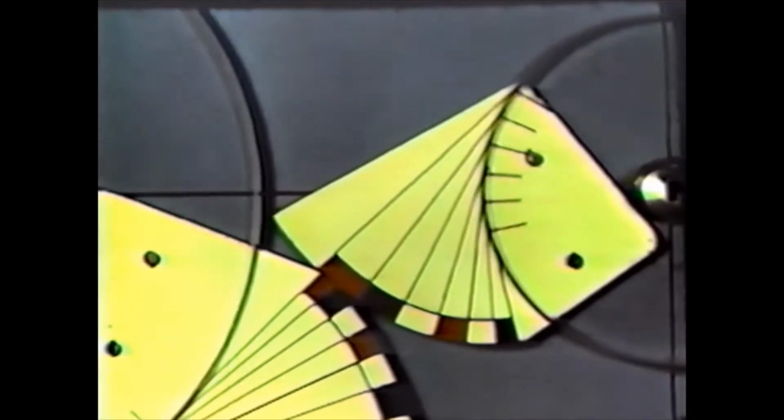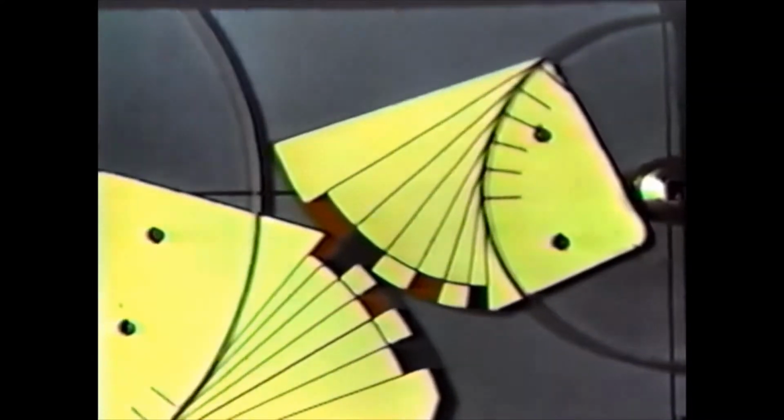Note that sliding takes place and that the rate of sliding is greatest when the end of one profile contacts its mate in the vicinity of the base circle. We will reinsert our original crossed belt to illustrate that these division points on both involutes, when they make contact, lie in the common tangent to the base circles. This is the line of action.